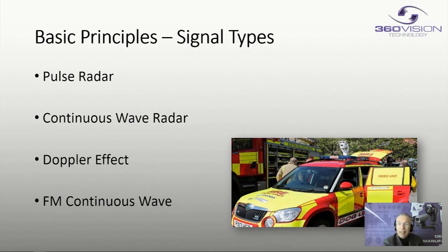The frequency modulation enables us to change the waveform as a time marker. So we send out the waveform continuously, but we change some of the timings inside it, and that gives us the ability, when the reflections come back, to compare when the timing change was done as to when we sent the waveform out and when it was received. Therefore, we have that range measurement.